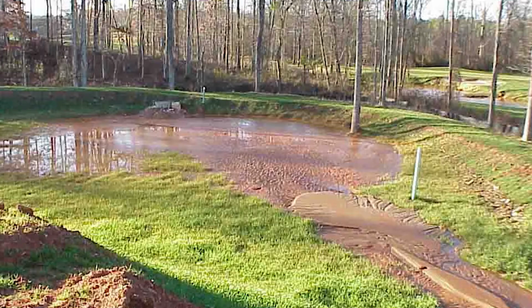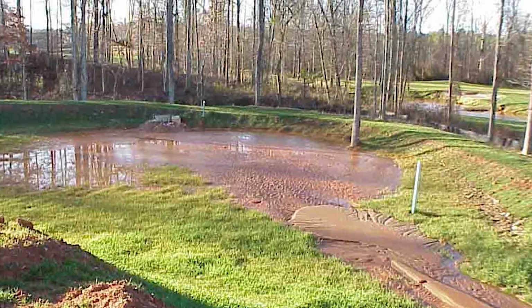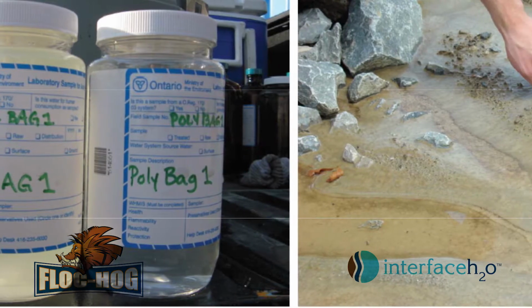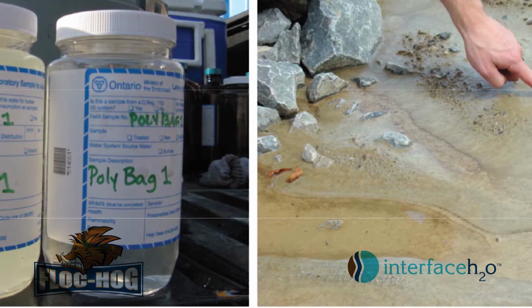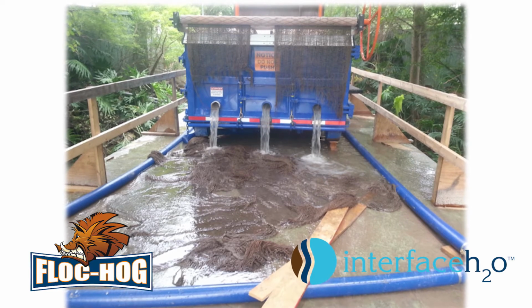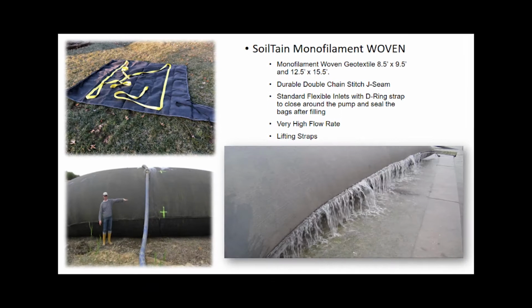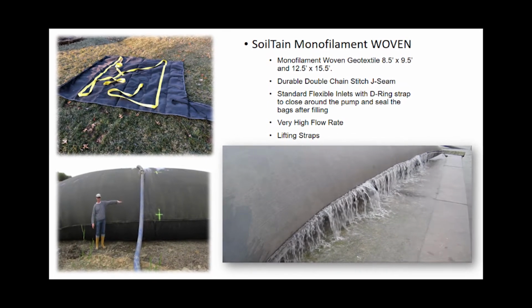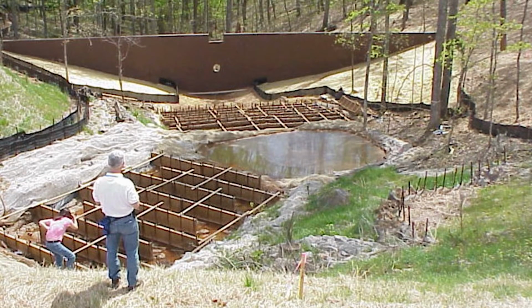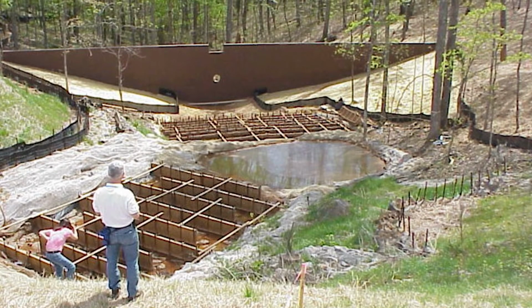How to inspect. Check for site-specific basic soil test report. Ensure polymer type and application rate are in accordance with the soil test report. Check for adequate mixing, settling, and capture. Check for exhausted polymer applications after rain events, during dewatering, and concrete demolition operations. Ensure captured floc is removed and prevented from traveling beyond the site perimeter.